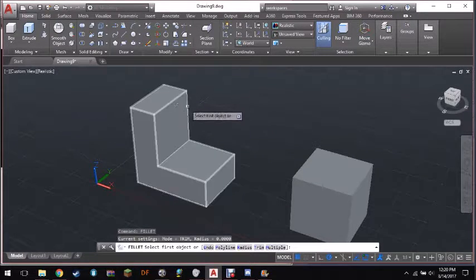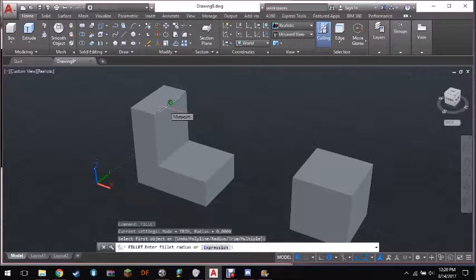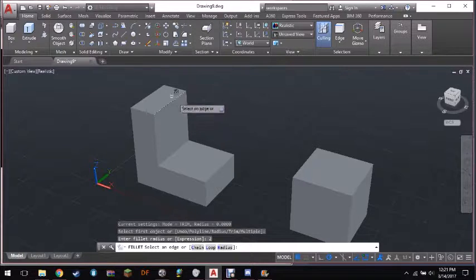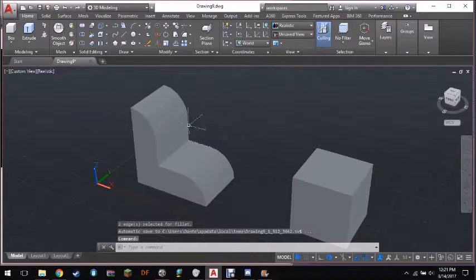Now to create a fillet, we have to pick the edge that we'd like to fillet. So I'll take that edge there, then it asks for the radius, which you can enter as a number, or E as an expression. So you could do E for 1 plus 2 minus 3, something along those lines. But for this one, I'll just do a radius of 2. And now I select the edges that I'd like to fillet. So this one's already selected, so we'll fillet one more, this edge. There you have it, 2 fillets, just like that.